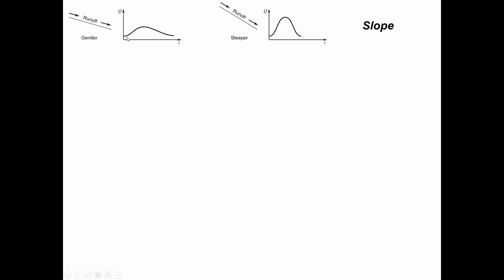And so what we're seeing for a gentle slope is that because the water is traveling more slowly over this slope, the hydrograph is going to have a more muted shape than a really steep slope. And now why is that? Because remember that when the flow arrives more quickly, then the hydrograph peak is higher, and there's less time for diffusion up and downstream.